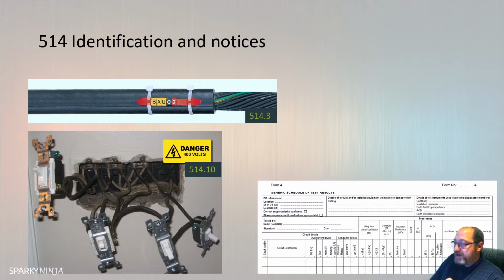So far as is reasonably practicable, wiring shall be so arranged or marked that it can be identified for inspection, testing, repair, or alterations of the installation. And except where there is no possibility of confusion, unambiguous marking shall be provided at the interface between conductors identified in accordance with these regulations and conductors identified to previous versions. Hence the two-colour label kind of thing.